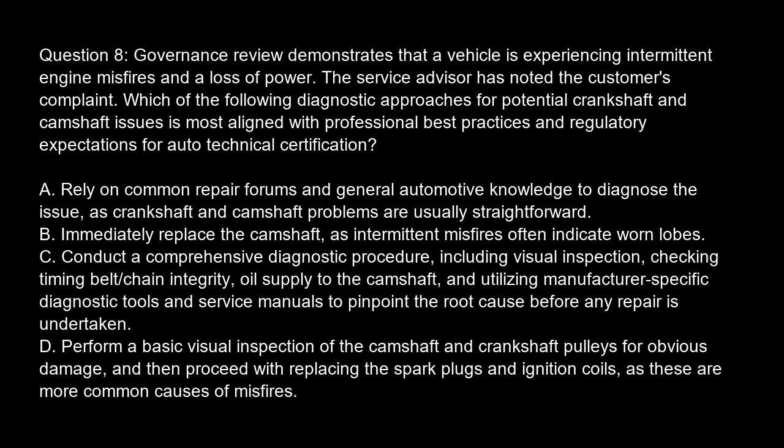Immediately replace the camshaft, as intermittent misfires often indicate worn lobes. Option C. Conduct a comprehensive diagnostic procedure, including visual inspection, checking timing belt/chain integrity, oil supply to the camshaft, and utilizing manufacturer-specific diagnostic tools and service manuals to pinpoint the root cause before any repair is undertaken. Option D. Perform a basic visual inspection of the camshaft and crankshaft pulleys for obvious damage, and then proceed with replacing the spark plugs and ignition coils, as these are more common causes of misfires.